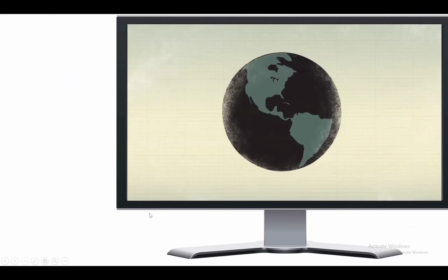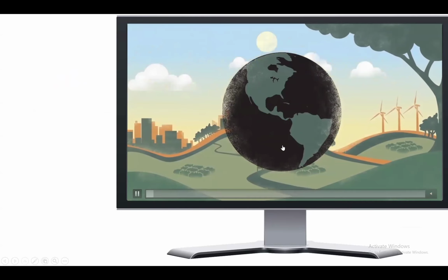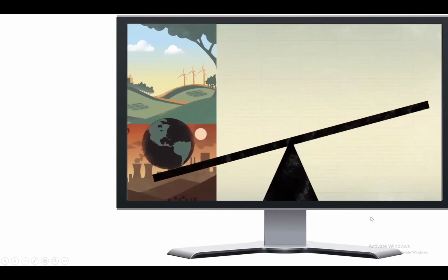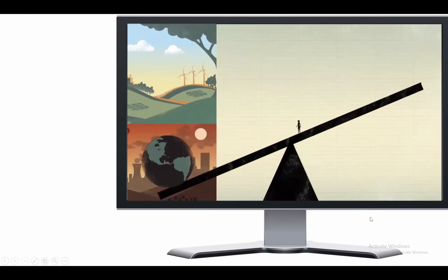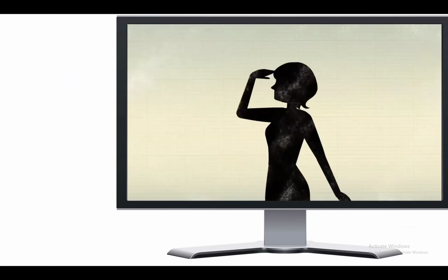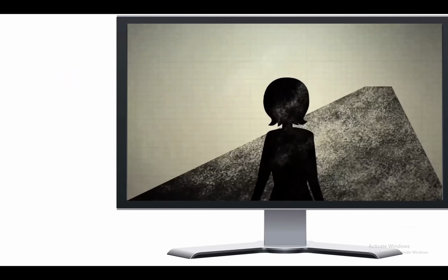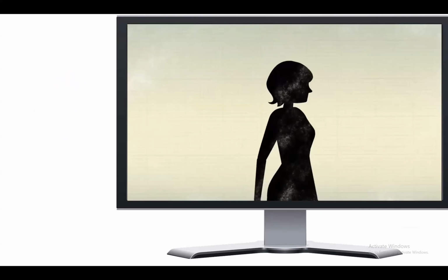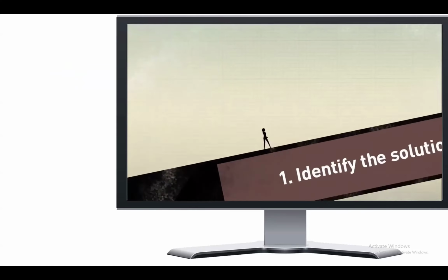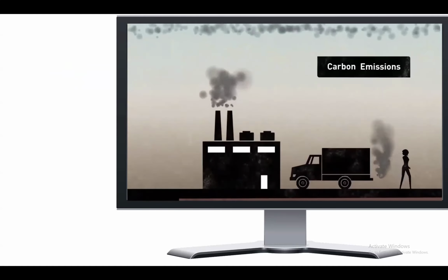6D BIM is basically about sustainability concept plus 3D model. If I give you an example, you can create energy models. You can use Revit software to generate these energy models, and you can manage the energy of the building by using these energy models. After creating the 3D model, you can analyze it and get some important data to minimize energy emissions from this building.